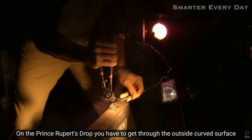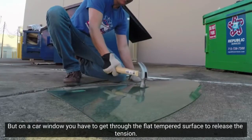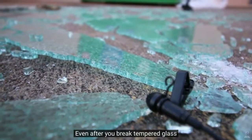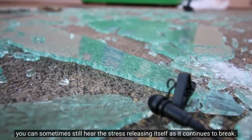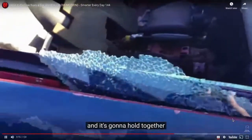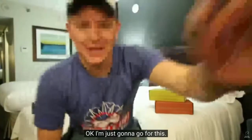On the Prince Rupert's drop, you have to get through the outside curved surface of the drop to release the tension. But on a car window, you have to get through the flat tempered surface to release the tension. With a sheet of glass, though, we have to start it along one of the edges. Even after you break tempered glass, you can sometimes still hear the stress releasing itself as it continues to break. So there you go. The next time you need to escape from a car window, remember that the windshield is annealed and it's going to hold together. But the side windows are tempered and they're going to bust out completely as long as you hit them on the edge.